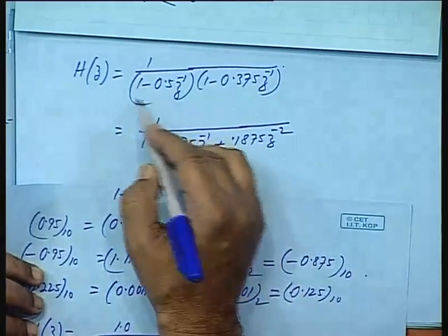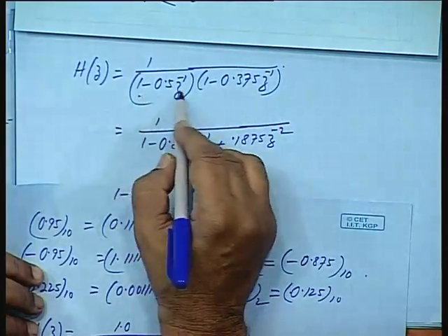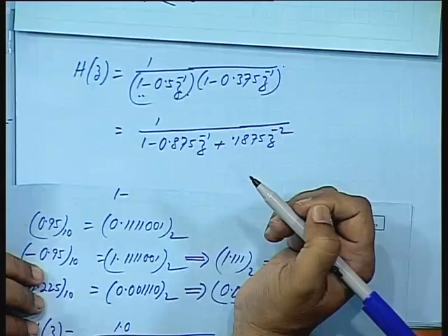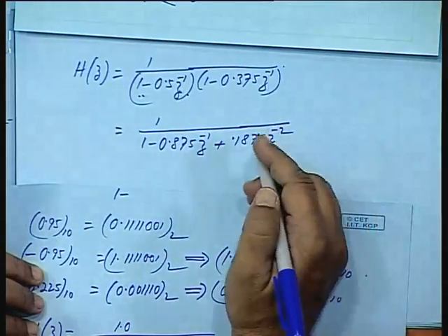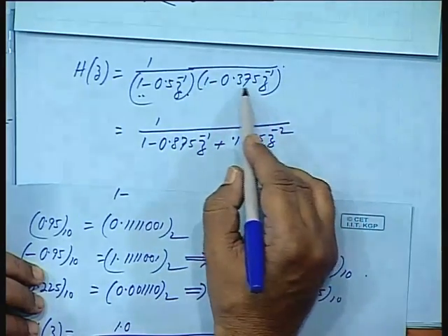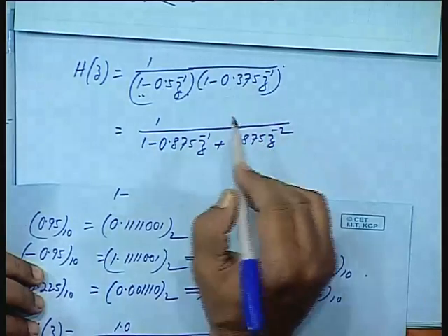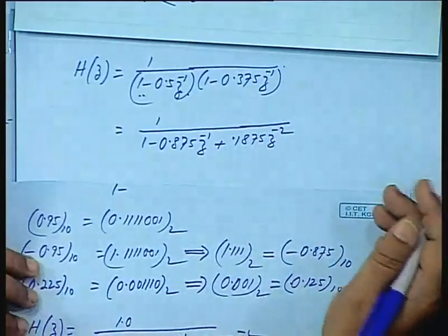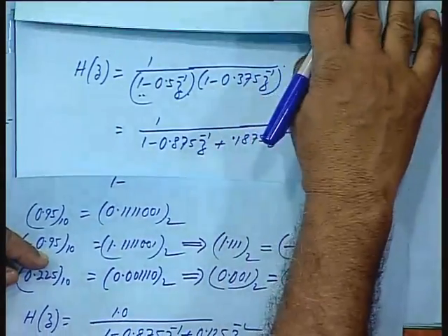Now, one thing is clear, if you factorize it, then some of the factors may remain as it is. In the cascaded form, as we have discussed earlier also, in each block the particular root will be sensitive to only the coefficient associated with that block, when you are rounding off or truncating. It will not be affecting the other poles or zeros. So, this is the advantage of cascaded form. You try to restrict the sensitivity of the roots, their dependence on the parameter truncation, within that particular block.